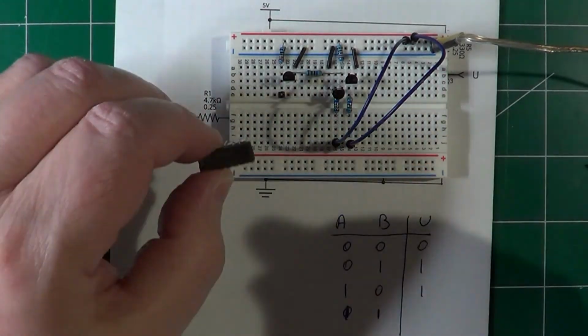So, today we have seen 5 different logic gates, the NOT, the NAND, the AND, the NOR, and the OR. We have also seen how it is easier to build inverting gates because of the way transistors actually work. And we have seen that obtaining non-inverting gates in practice requires more components, and so we reach the paradox where simpler logic gates have more complex implementations.